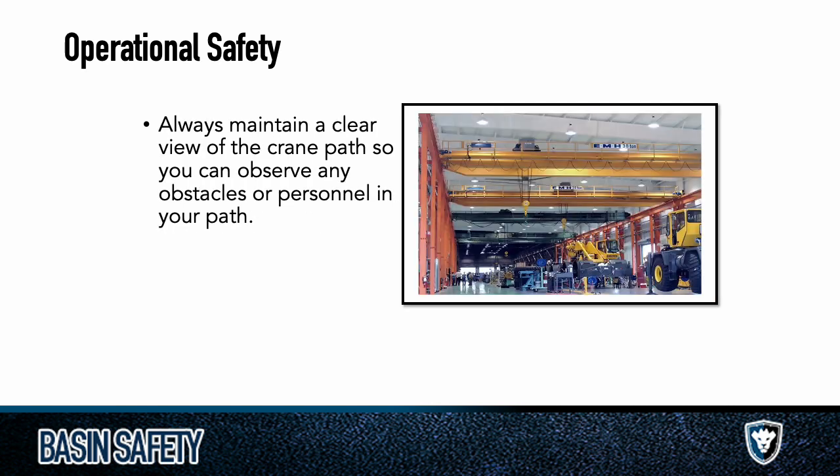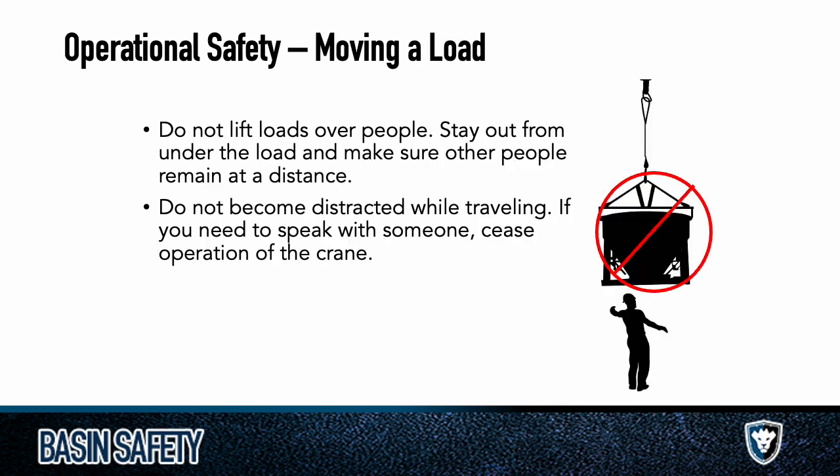Always maintain a clear view of the crane path, that there's nothing blocking you. Move that stuff out of the way if you can. Now, there are times where you're going to be moving it to an area where you're moving it over something, for example, and that crane path isn't clear. So you want to make sure that your spotters are in a good place where they can see where everything's going and see the crane operator. You can use multiple spotters. That can get complicated, but it's better to have multiple spotters where everything is visible rather than having blind spots.